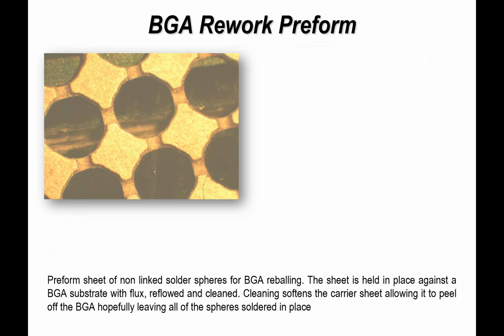But basically the idea here is we're trying to join together multiple deposits of solder, but what we want is them to reflow, but before they can actually move and wick to another termination, which we don't want to happen, the small reductions in dimension between the individual deposits will break first. So that's a controlling factor. In my work originally with this preform and others, it wasn't as successful as I'd hoped.